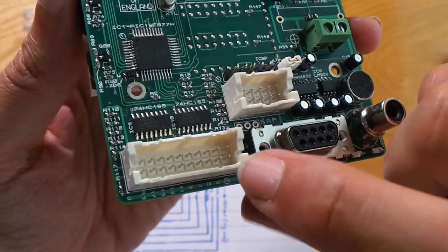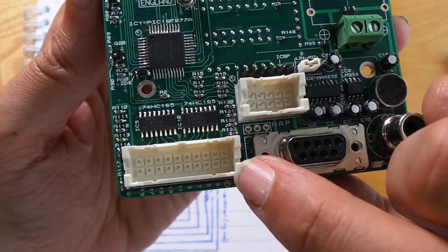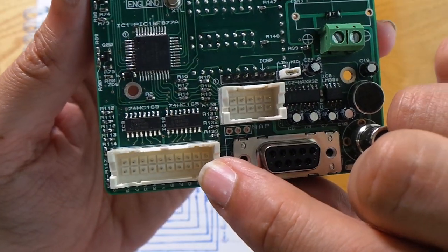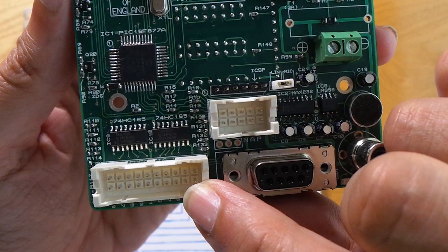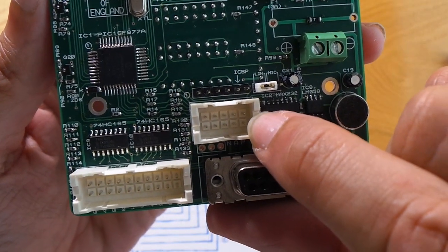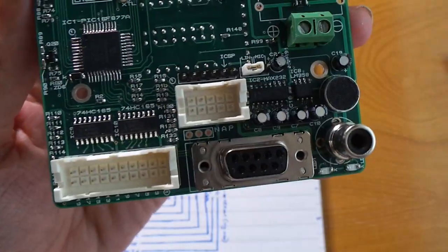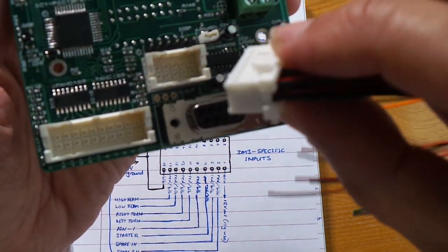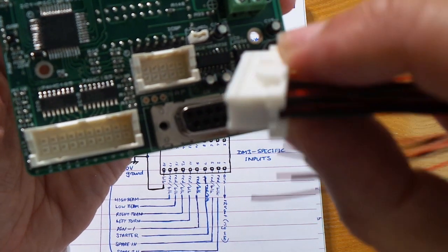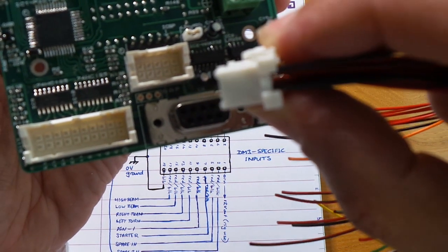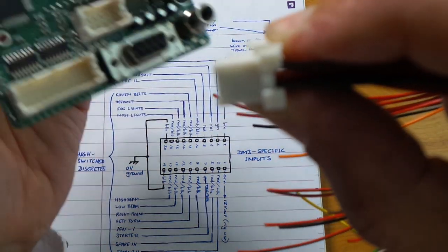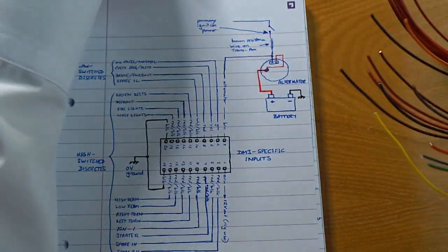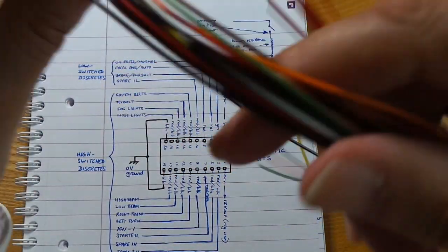Let's continue then and take a look at the second of the JST connectors, this 20-way connector. Now this connector is for inputs which are specific to module DM3, as opposed to this one which is generic and the same on all modules. So this one then, again, it's a 20-way connector, and it has a similar kind of connector but just bigger, and it has the same arrangement where this little locking tab is at the top, and you push down here to open that, push it in, and it will snap into position. So let's go through the connections on this one then.